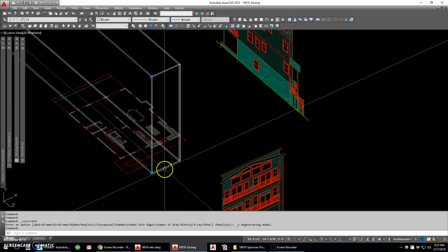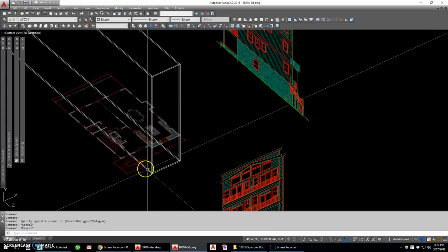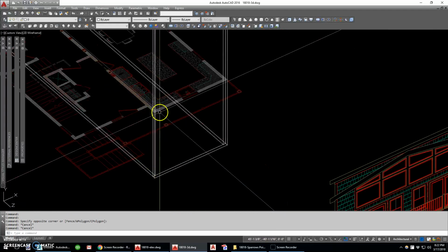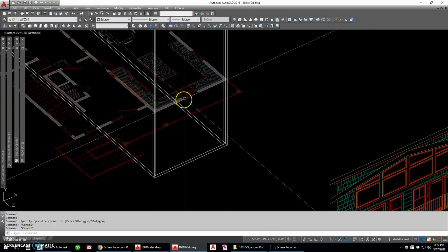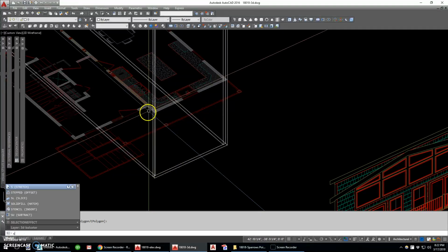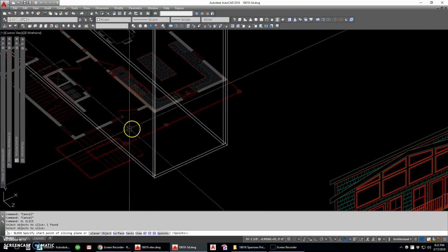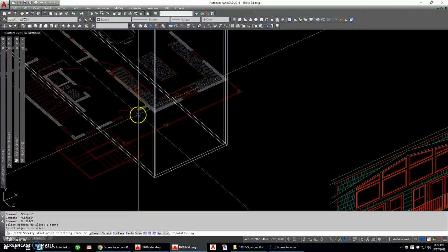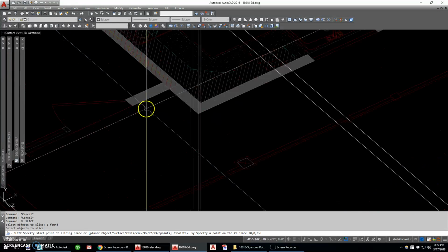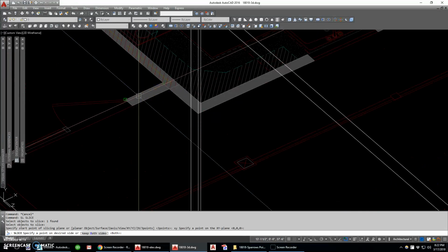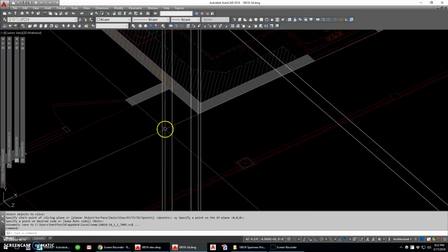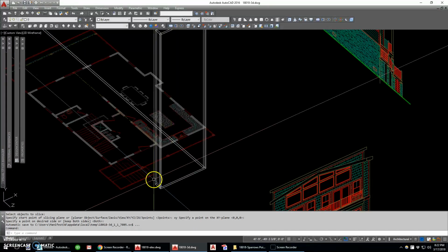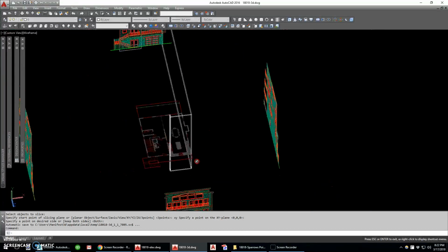And I'd like to keep these walls as separate objects. Then what I'm going to do is trim these two side walls back to where they go. Since my front plane is out here, I want to slice this left side on my XY axis to the inside of this wall, because I'm going to create this wall in a second. And then I'm going to say keep just this side. So as I zoom back, I've got that little return wall.